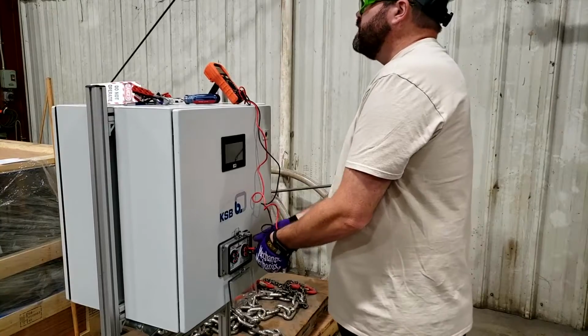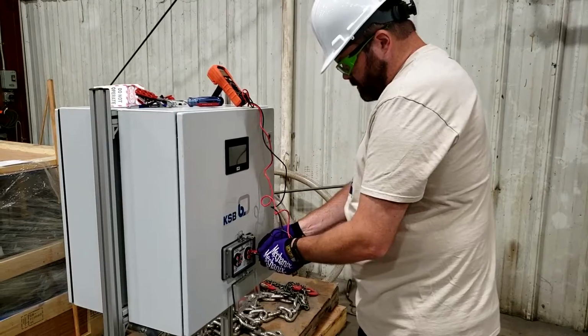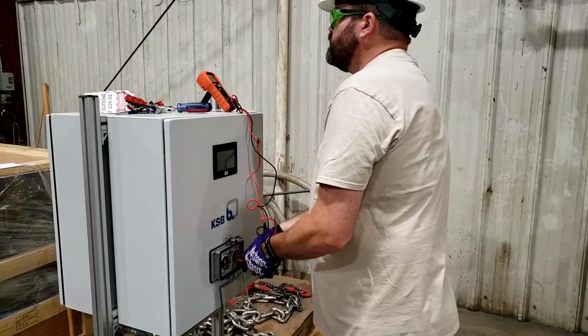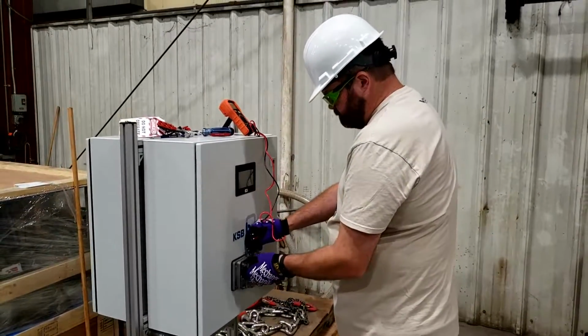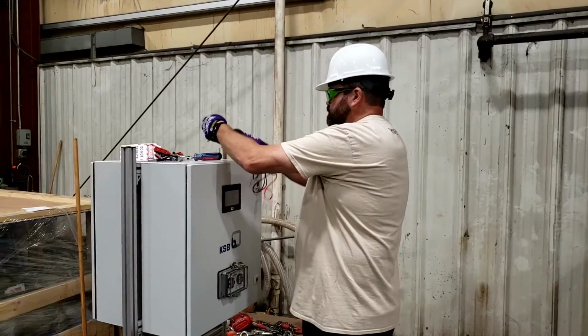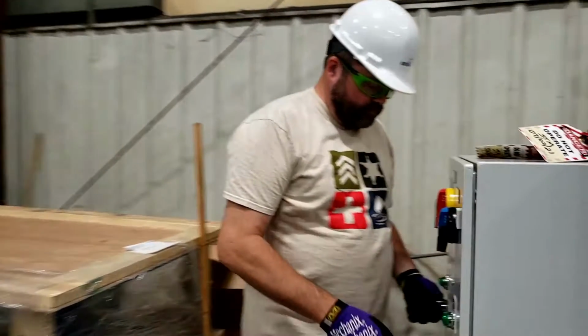Ground to leg 1, ground to leg 2, ground to leg 3, leg 1 to leg 2, leg 1 to leg 3, leg 2 to leg 3. After each test, you will be confirming that the voltage is okay between the various test points. Please note that this must be completed prior to proceeding. Once you have completed all 6 tests, close and latch the door to the voltage test station and turn the multimeter to the off position and communicate out loud, all voltage verified good.